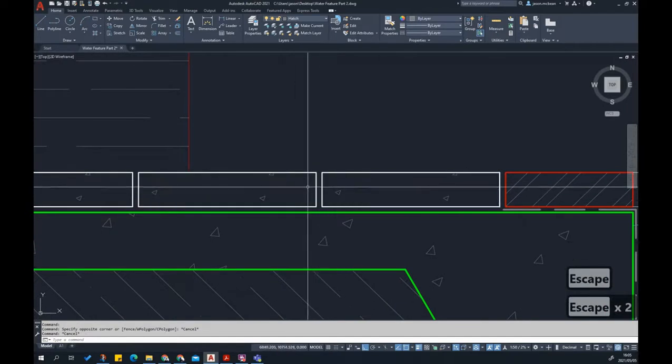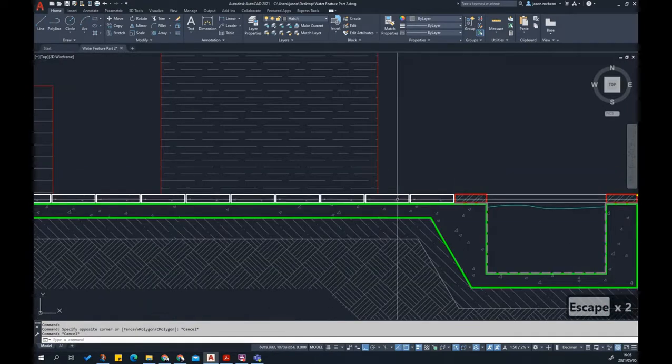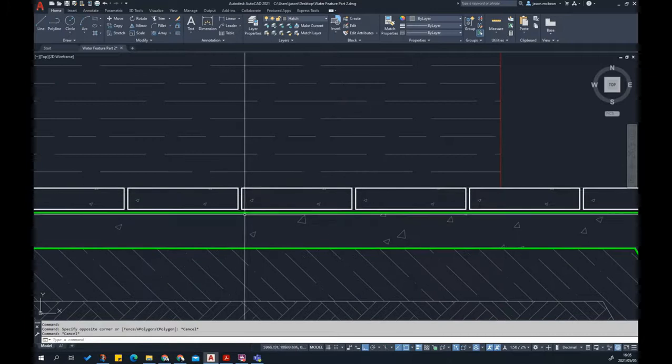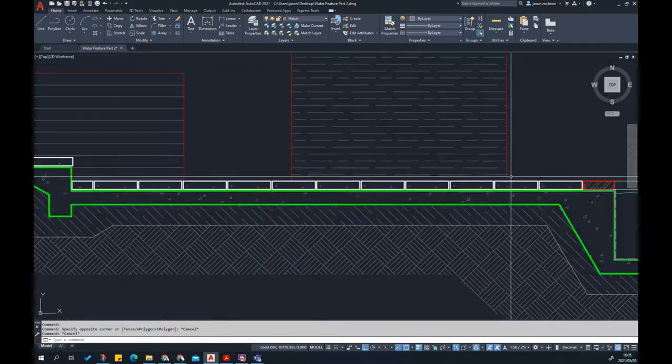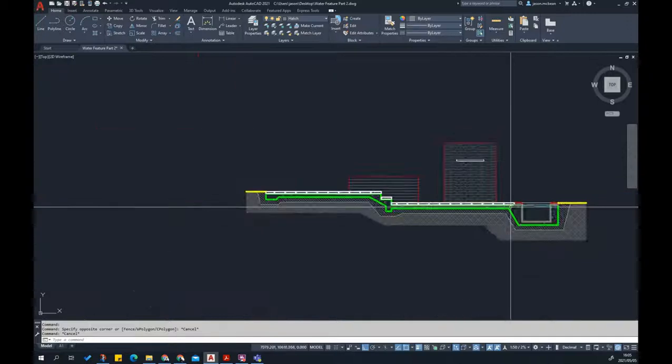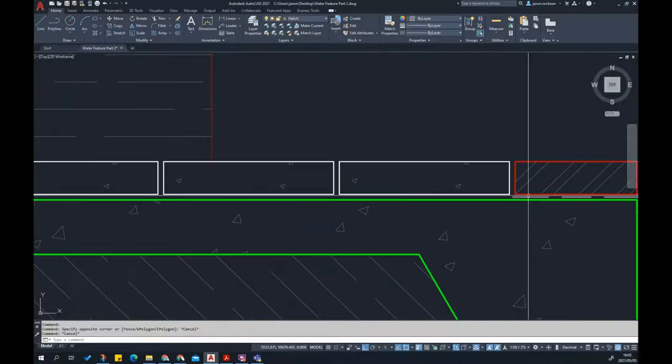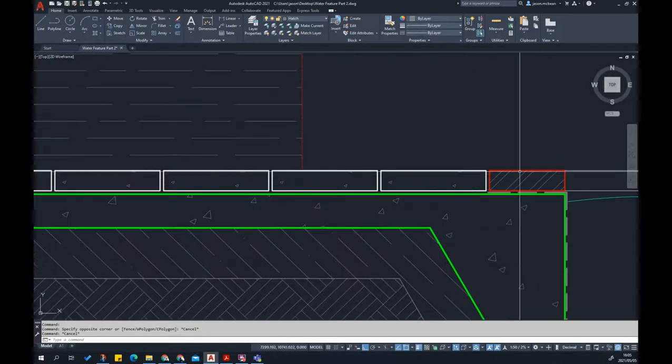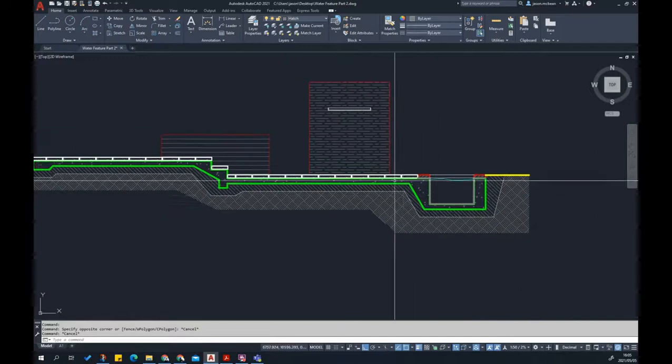Just remember, we need joints, a sand joint. They put a very fine sand over this when they're done, and it goes in between the joints, and they brush it off, and it beds these things, and they fit nicely, okay. It's not like applying tiles, it's a bit different. They use a type of sand, okay.